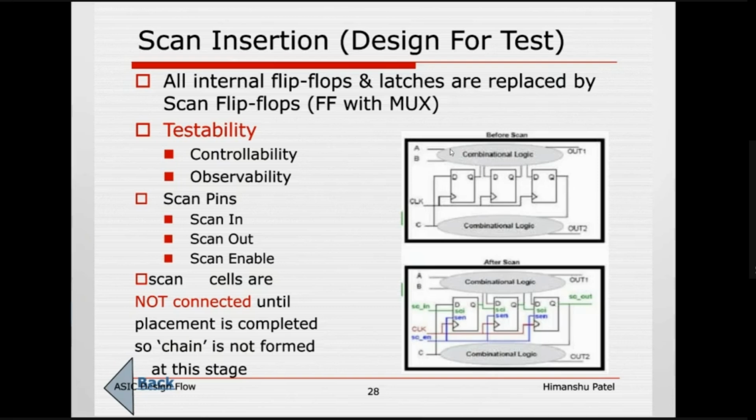A, B are directly going as inputs here. C is also going direct input, and one of the C is again going to this flip flop, and this flip flop output is again feeding into one of the inputs of this combination logic gates. Now, these flip flops are sequential. They are connected in a proper sequence, but not as shift registers, but in a sequence based on a single clock. They are driven by a single clock. Till this part, it is clear to everyone.